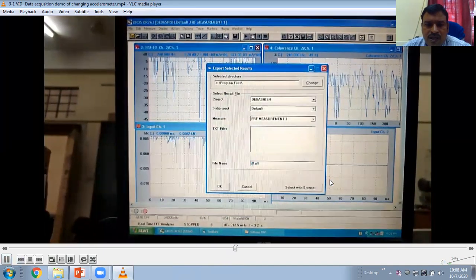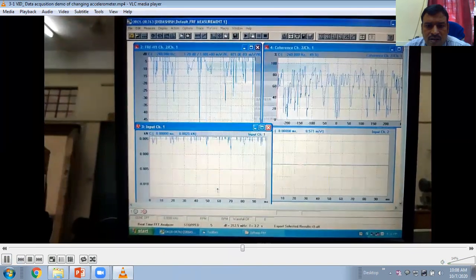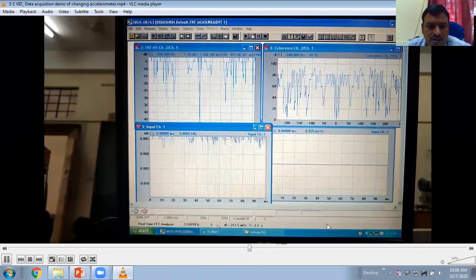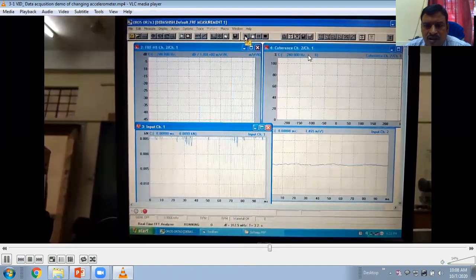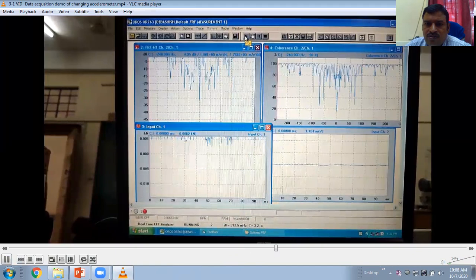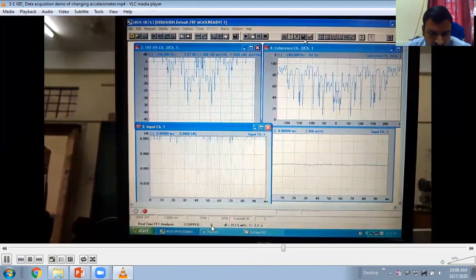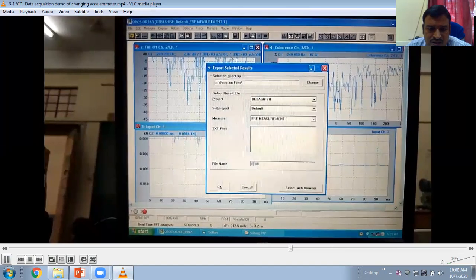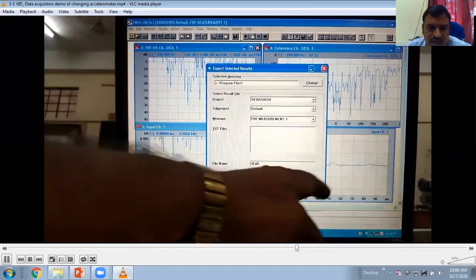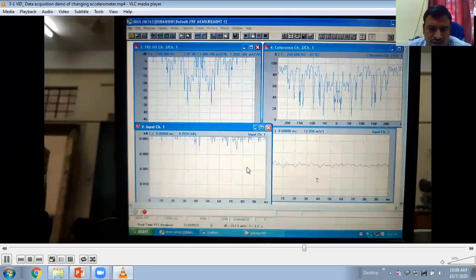If these data are not good, I take the repeat data. When the responses are not good, it's better to retake. You can see that after 5 averages my FRF will stop automatically. Though the real time will show the impact continuously, it will not be recorded in the analyzer. This data is supposed to be saved, so that's why it will stop.